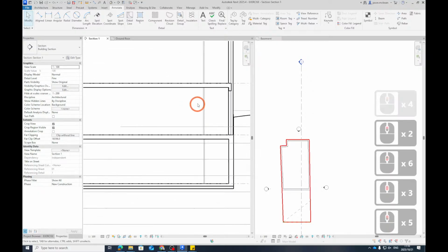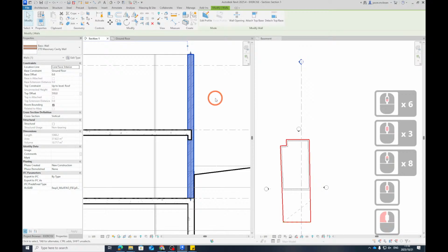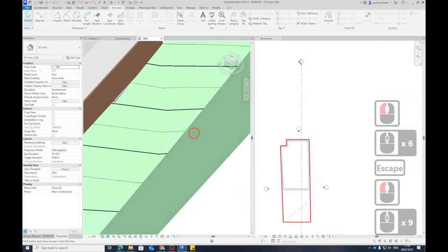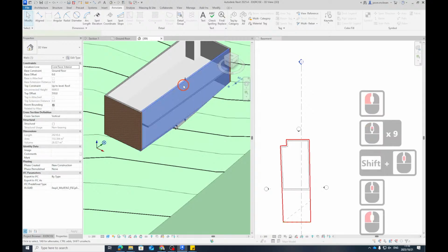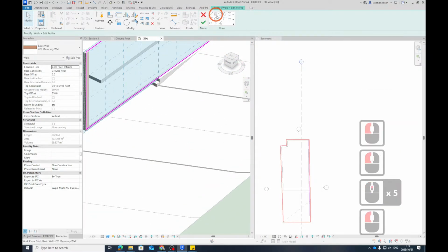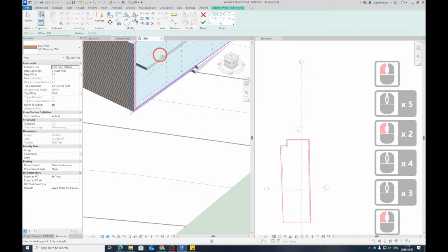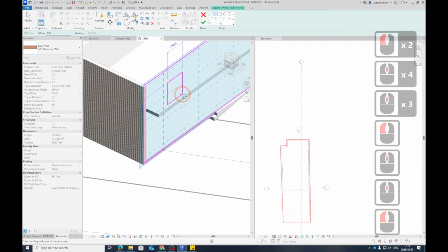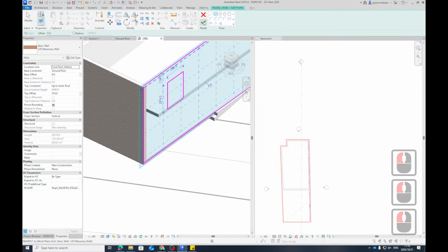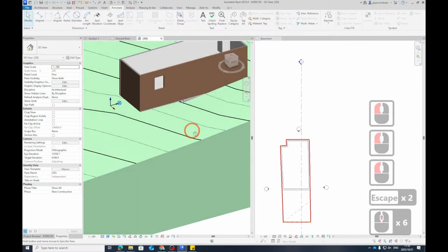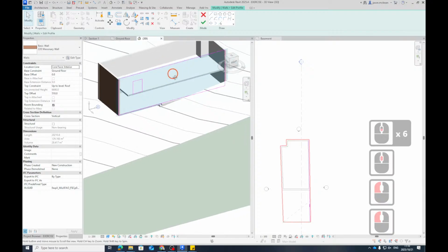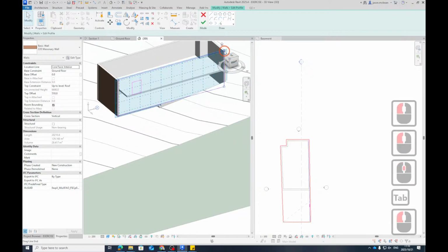Okay, all right, so there's your brickwork in. Now with your brickwork, just a quick rule of thumb. You can go and change their profiles, so you can edit profiles. If you want to cut in quick openings, you can go and cut in openings. I would use an elevation or section view of this, but it'll snap to stuff. You can go and create openings like this. You can also change the profile here.